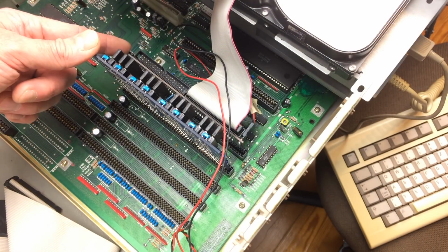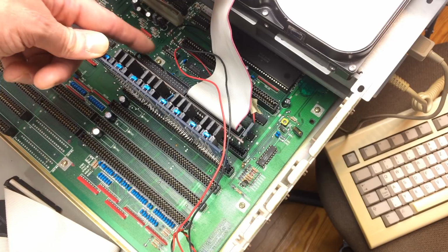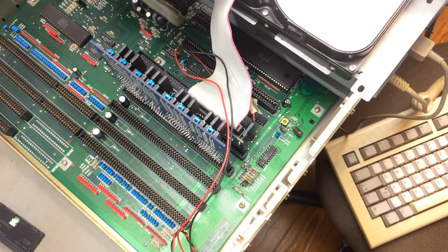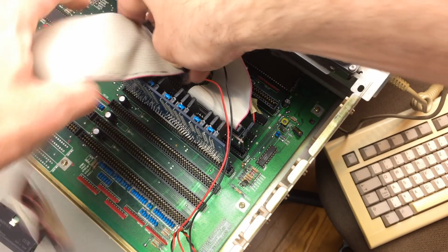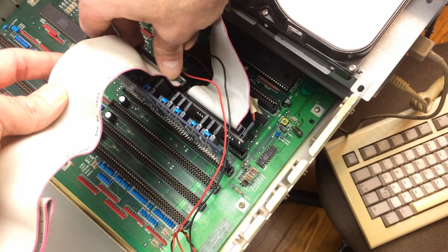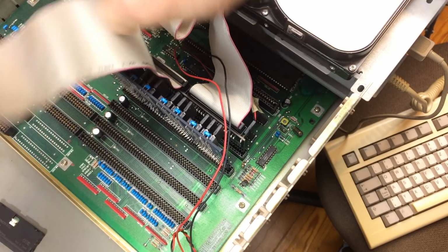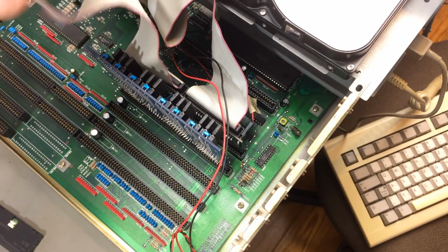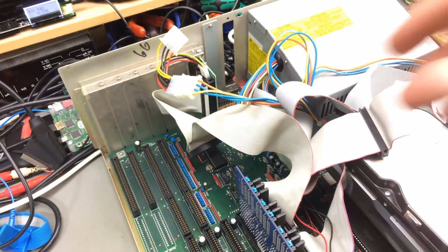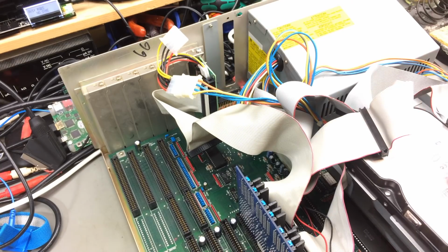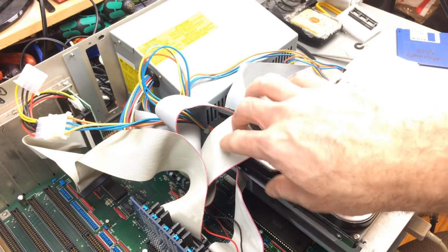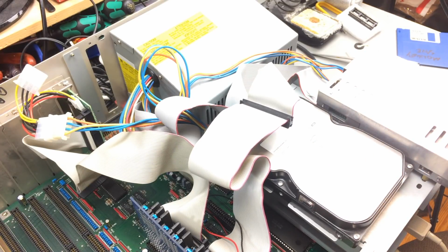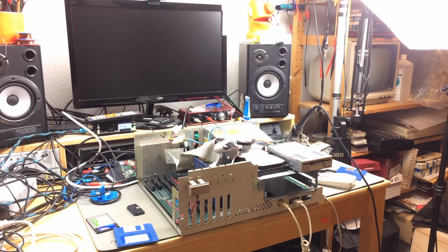Don't forget to open this jumper, because that provides power to the disk on module, and you are probably going to break anything that's not a disk on module that you connect to the port the DOM was before. So I'm just going to connect the CF card reader thingy now. So this is now connected to the compact flash. The other cable is connected to our hard disk. Okay, let's just see how this goes.